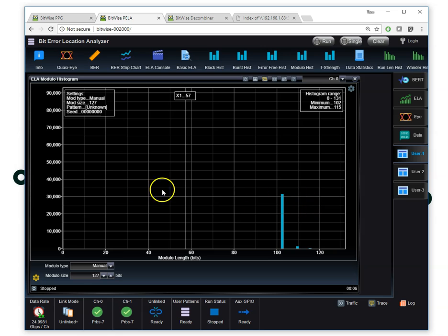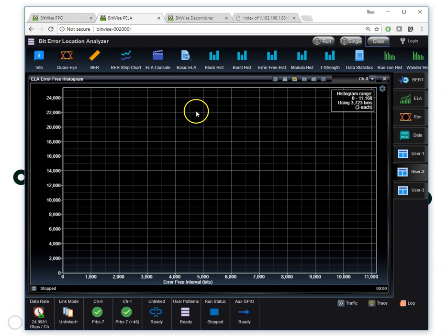Correlations can be done to lots of different magic numbers, and we all know magic numbers in our system, whether it's a 32-bit bus or a block size. Something that should not have errors that depend on them all of a sudden starts to cause errors that depend on them. Then you start to know, well, maybe I have a weak driver or something in my system is causing errors to propagate on those lanes more often than others. How might you find those magical numbers?